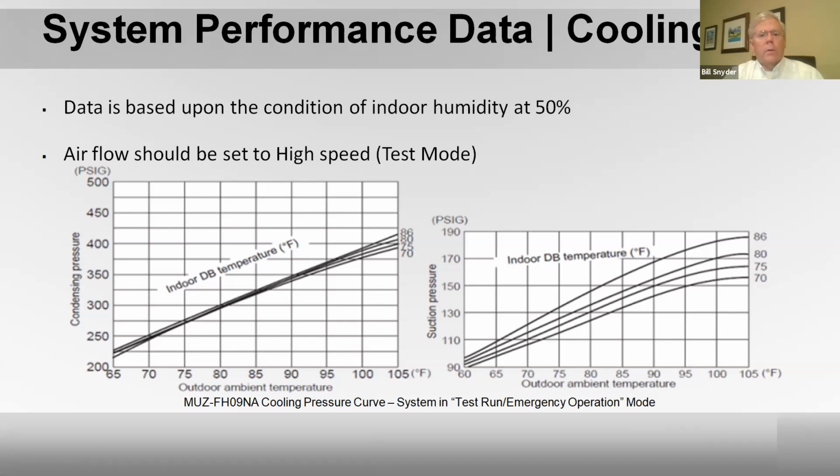They can verify if the equipment is performing correctly. They are not charging charts. In order to use these charts, you need to put the unit in the test mode, because in the test mode, it basically is running at like 60 hertz, and the fan should go to high speed, the compressor will go to one speed, and all these tables then will tend to work.